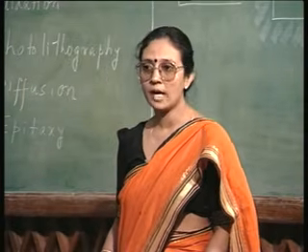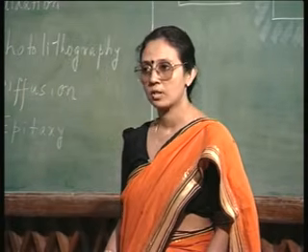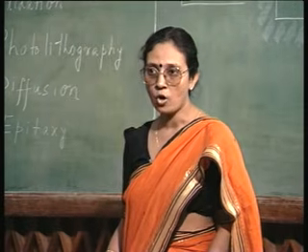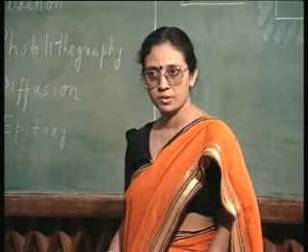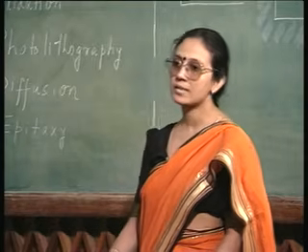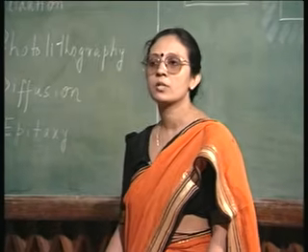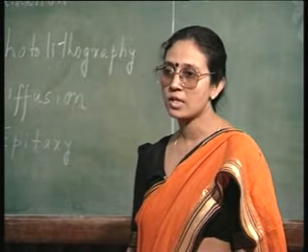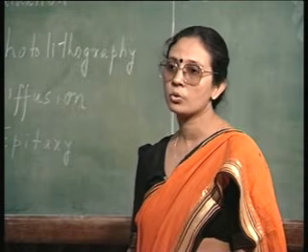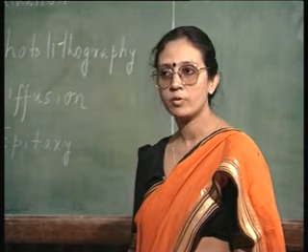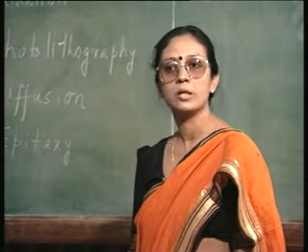You already have a single crystal substrate. You are going to grow another single crystal layer on top of this substrate. This is epitaxy. Please realize that the single crystal substrate is a few hundred microns in thickness. In contrast, the epitaxial layer you are going to grow on this substrate is from a fraction of a micron to a few microns thick.